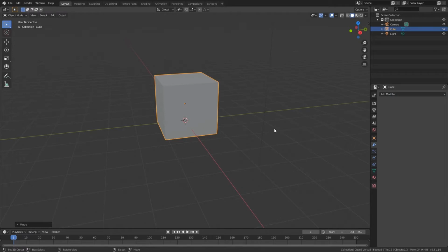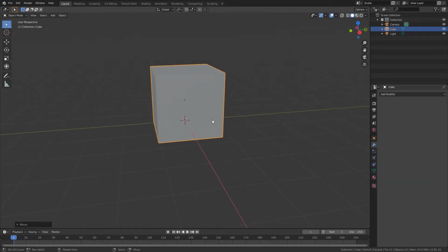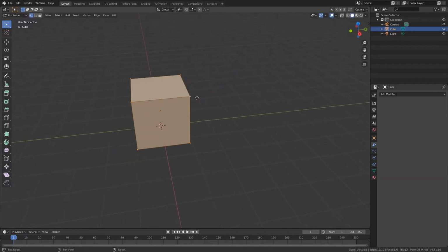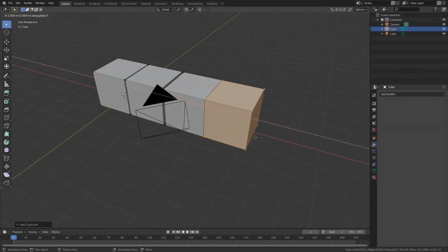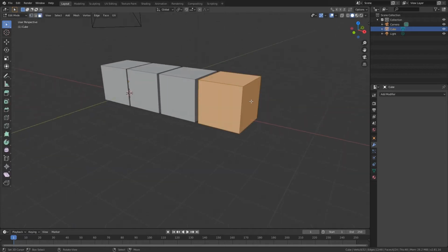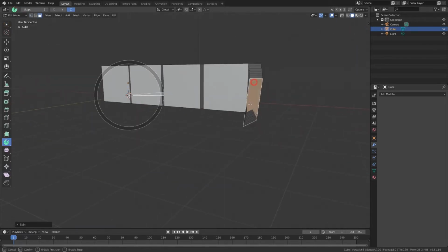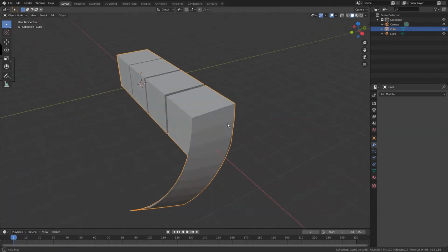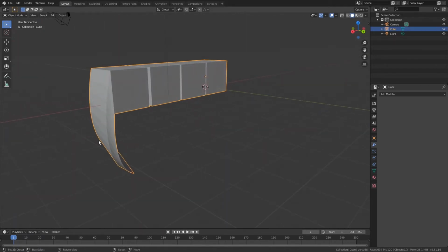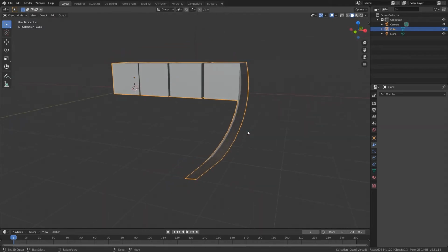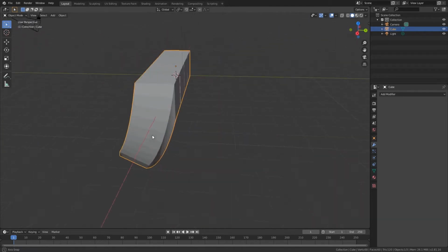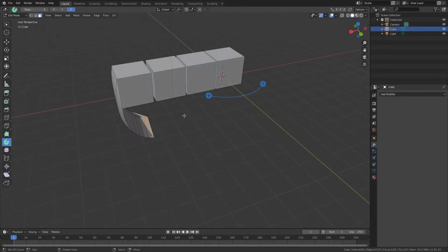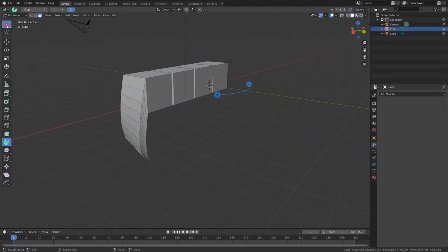Okay, now the main reason is, after you're done editing an object with edit poly, let's say I create this thing and I make a couple of duplicates, or let's say I create a screw effect over here. All right, once I'm done editing, I cannot change this. That is one thing. And also I can't animate this. Okay, this is not a procedural effect. This editing is done in the mesh, and I can't come back and change it or animate this value.